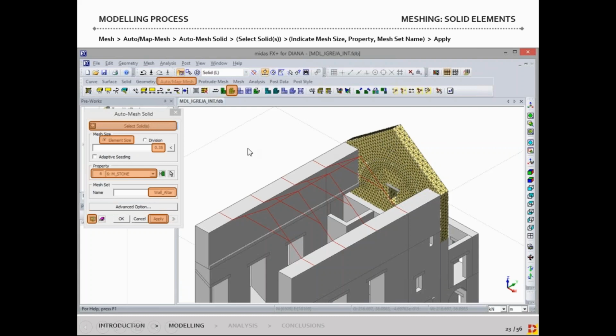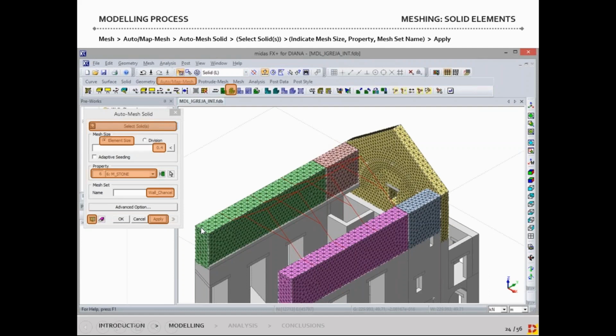And we can see here how the mesh, in this case it was 13 centimeters, gets more refined when we get to the shell ones, which was just 30 centimeters. Now we continue, and we will see how now with a different mesh size, when we get to the connections between the solids, also the mesh will adapt to automatically join the previous one. Here we can see how the distribution is regular, and here it changes. And we will see later how to check that actually every connection is properly done.